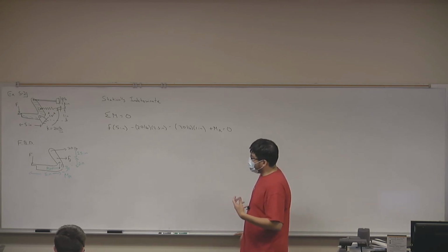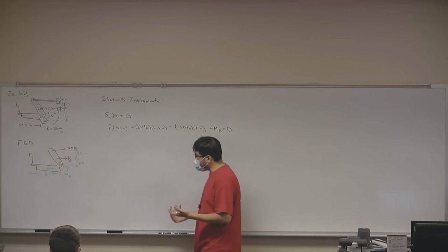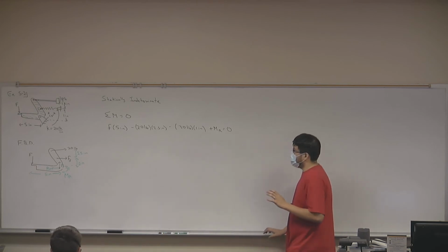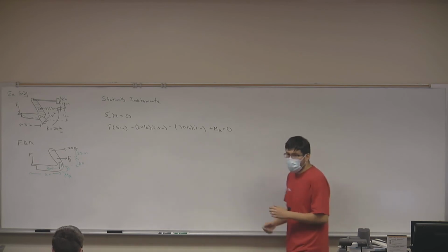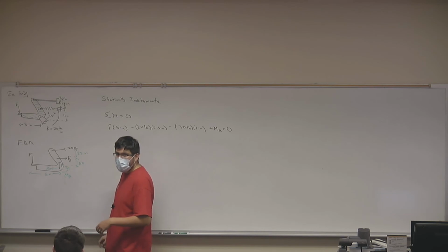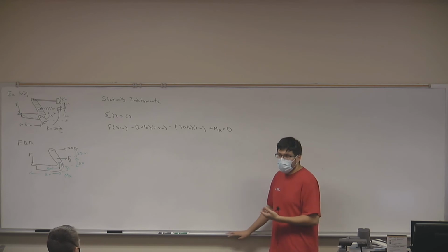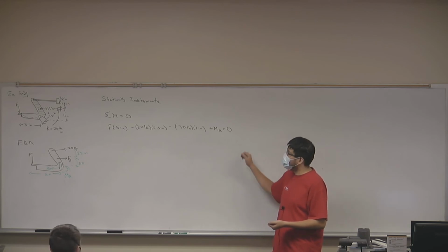This section is more of a warning, right? Sadly, we can't use our equations to solve for everything. Okay? Perhaps if you have a system where you know your forces are distributed equally, maybe we can come up with something. But right now, in this system, we have two unknowns, but only one equation that relates them, so we can't solve it. So if I were to give you this system on the test, with a hinge here, and I say calculate the forces, what's your answer going to be? We can't. It does not exist. Yeah, we cannot calculate those forces because it's a statically indeterminate system.